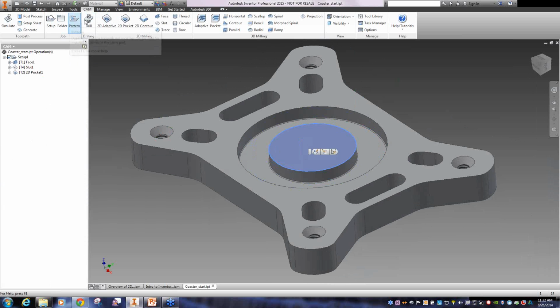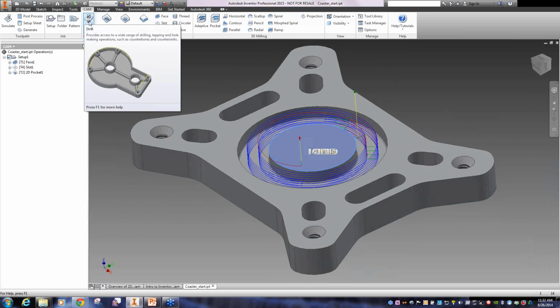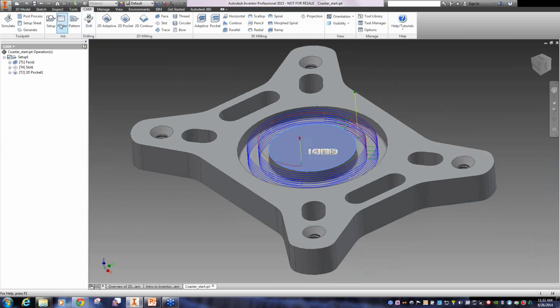Because typically when we do hole making, it's a spot drill perhaps, a drill followed by a tap. And then you can reorder things with HSM to have that entire machining sequence of the hole, the spot, the drill, and the tap, all in one folder. It makes it so that we can manipulate the hole making with a much easier selection. I don't have to pick the drill, pick the spot, pick the tap to edit things or move things around.